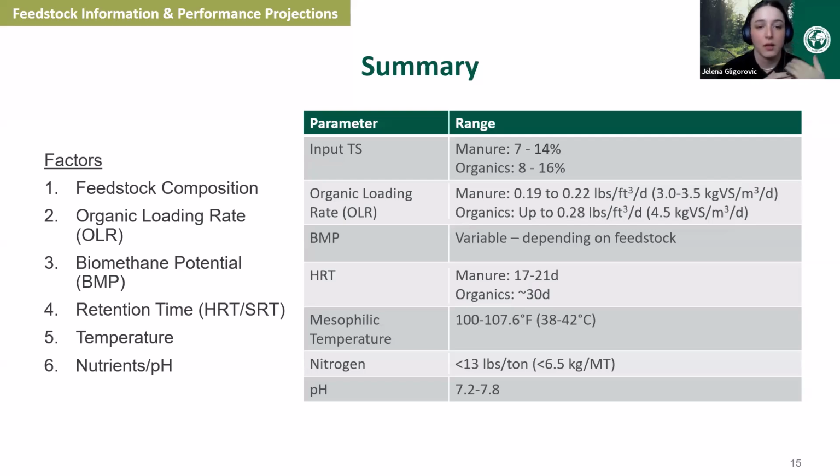depending on the feedstock, the base retention times, or the HRTs that we're kind of designed to. And then I'll focus on the temperature as well when I talk about heating systems. So keeping it in the mesophilic range, 100 to 107 degrees Fahrenheit or 38 to 42 degrees Celsius.